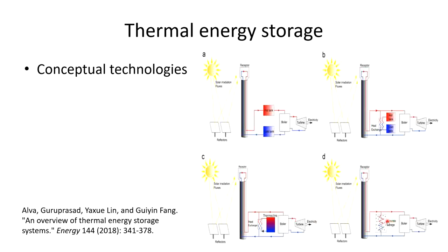And here on the last figure we can see a solid block for energy storage, here particularly concrete storage, where the hot fluid can flow through channels in this solid block and so charge it, and then during discharging a separate pump would pump the cold fluid through the storage, get the hot fluid, which then goes to transfer the heat in the boiler, in the steam generator.